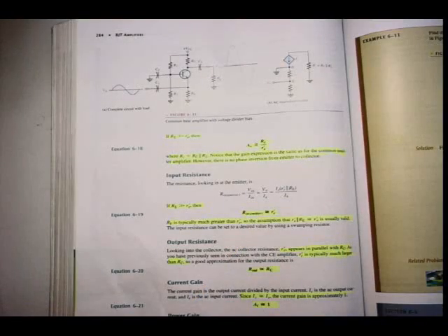They only differ by the value of IB. IE is the largest, which is IC plus IB, but IB is very small in comparison, so I can assume that IC and IE are equal or almost equal, and I can make the assumption, like in equation 621, that the current gain is approximately 1. It will always be less than 1, of course, but it will be close to 1. The same as we've had with the voltage gain of the common collector amplifier.